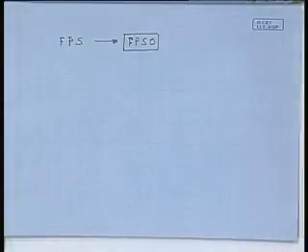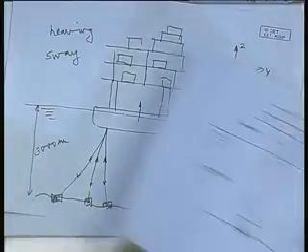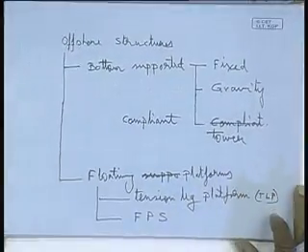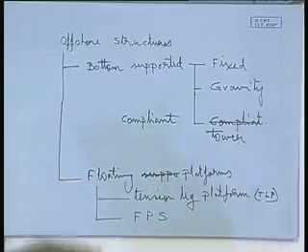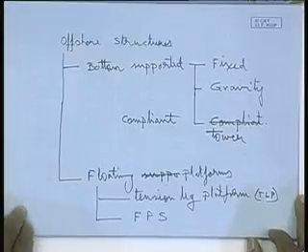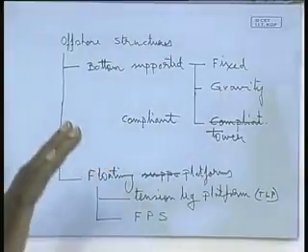In all the previous offshore platform types, one thing you can see is that all of them are location specific. They are fixed to the location. That means when we are talking about the fixed platforms, well, it is literally fixed. There is no way you can move it. When you talk about gravity platform, though it is not fixed, for all practical purposes it is fixed. Once you install a gravity platform in one place, when that oil gets dried up, you are not going to remove that platform from there, because it will be a huge job and totally unnecessary.